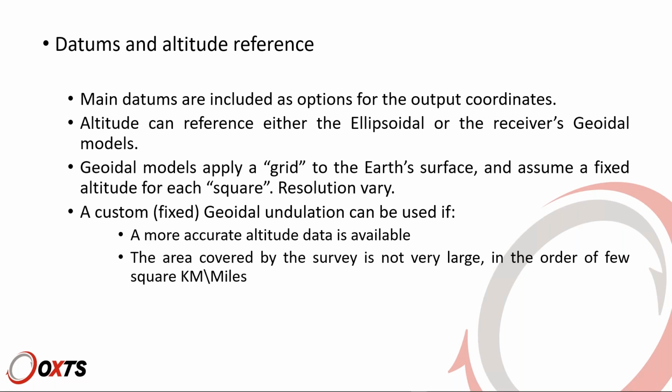If you have a better knowledge than the receiver does about the altitude in a specific area, then you can customize this geoidal undulation and type it in. So the system, instead of using whatever comes with the receiver, can use what you instruct it to use.